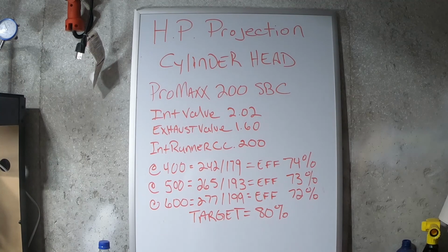Dual profile cams will have larger exhaust lift and duration than the intake. And that is to help compensate for the disparity in the efficiency of the cylinder head, to help get the exhaust gas out faster. So selecting a camshaft can help offset the efficiency of your cylinder heads and improve them. But knowing these numbers is very important.